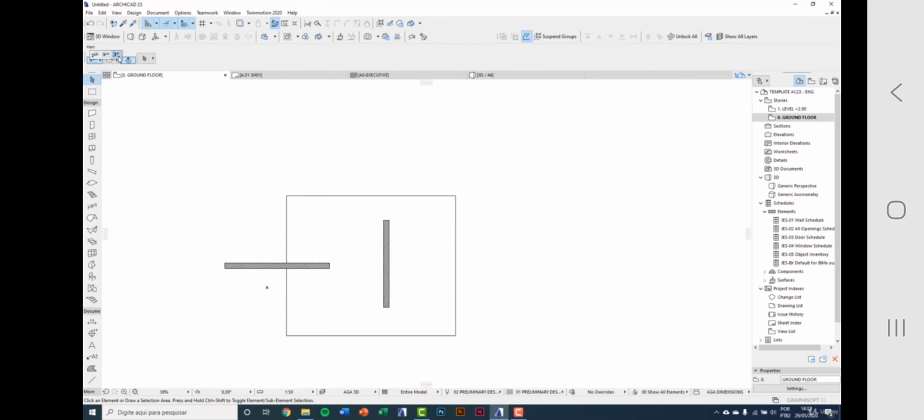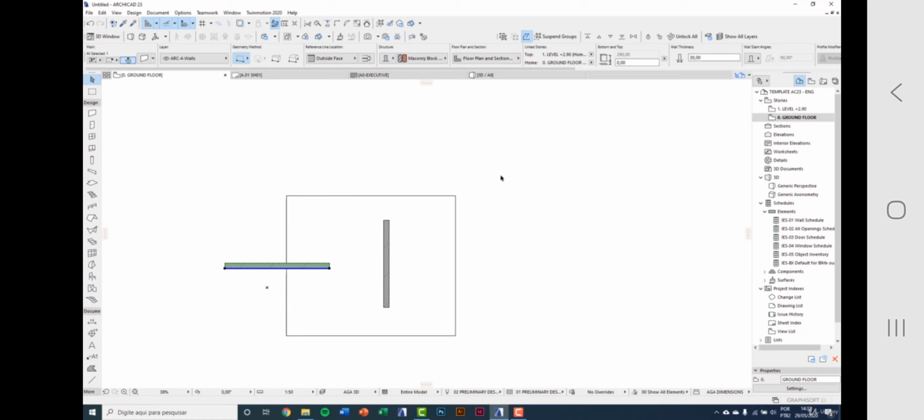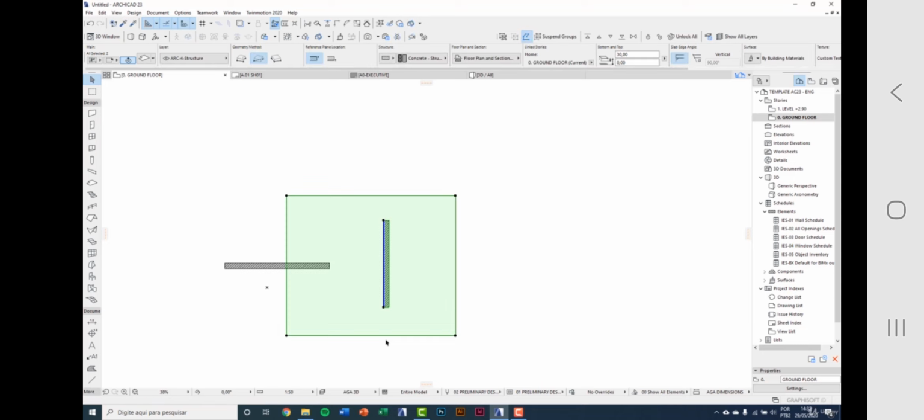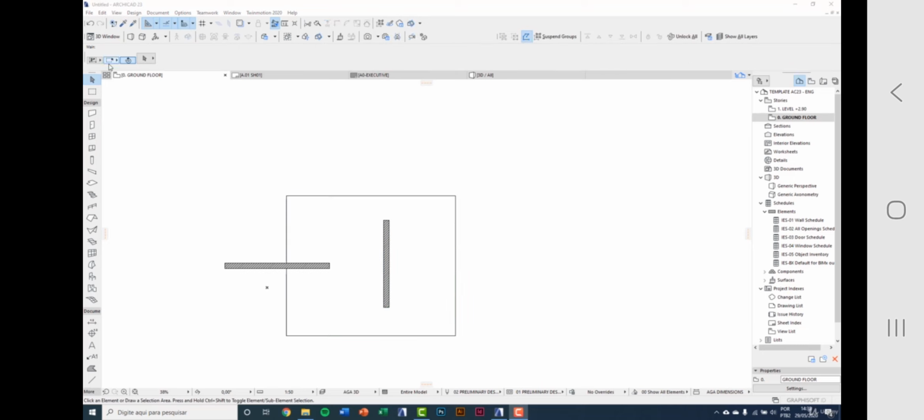And the third option is like in AutoCAD: making the rectangle from left to right, the object needs to be inside. And from right to left, you need just to touch elements and they are selected. Here we have some geometry methods beyond the rectangle. You can choose one of them.